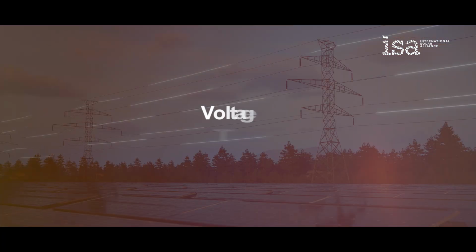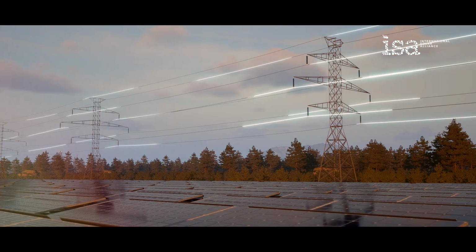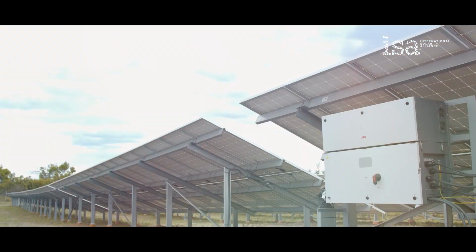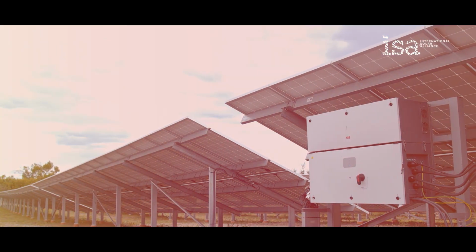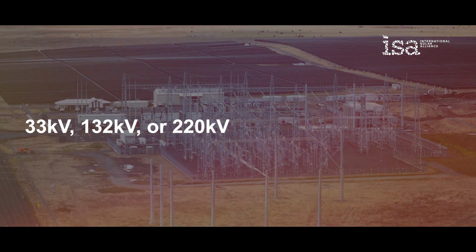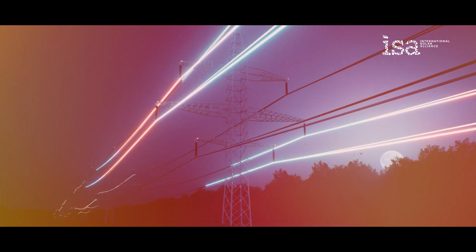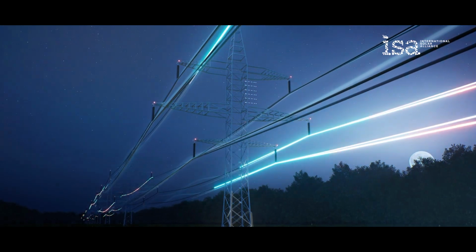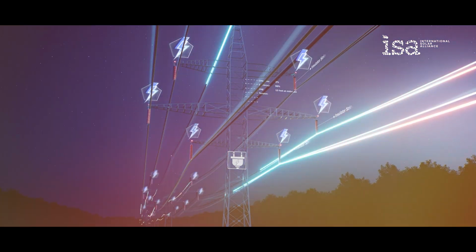Voltage transformation. Solar panels generate low-voltage direct current (DC) power. The inverters convert this into low or medium-voltage alternating current (AC). Substations then use large transformers to step up this voltage to high-level transmission voltages. This is necessary to minimize transmission losses over long distances between the remote solar farm and population centers.